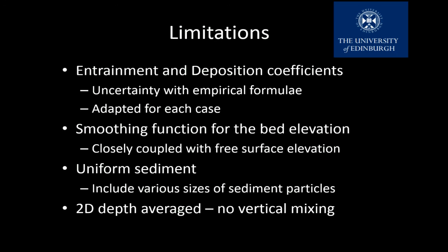Like I said, I mentioned some of the limitations already. Another thing is that the entrainment and the deposition coefficients are empirical, and there is some uncertainty, as always, with empirical formulae, so they need to be adapted for each case. Also, because the bed and the flow are so coupled, it's necessary to include some kind of smoothing function for the bed elevation, perhaps, and then I'd like to extend this to include non-uniform sediment particles.